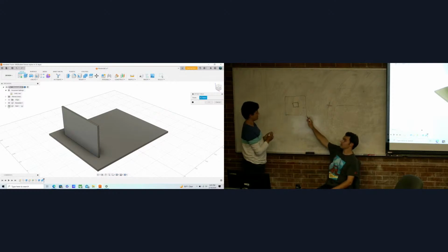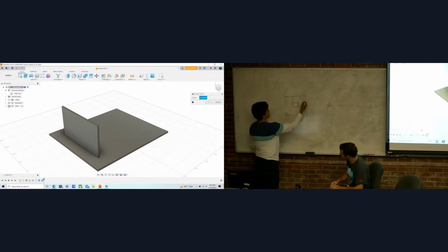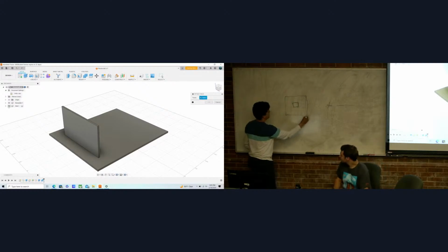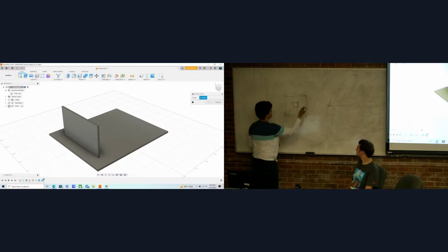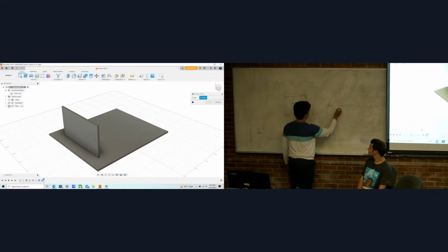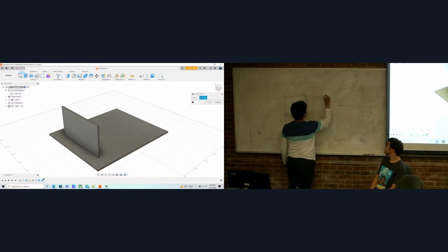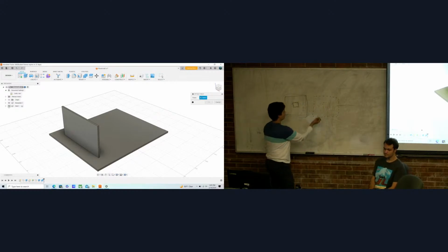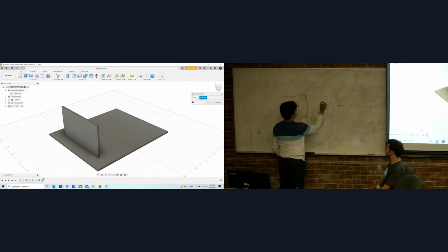The outer edge is larger. Yeah, if this solid line was the imaginary line, then the real line would be out here, larger than the piece, because this is additive manufacturing. If we do the same thing with subtractive manufacturing, these are the imaginary lines of the CAD, right? When you actually cut, the actual lines are going to be larger than the imaginary line. And on this side, it'll be like this.